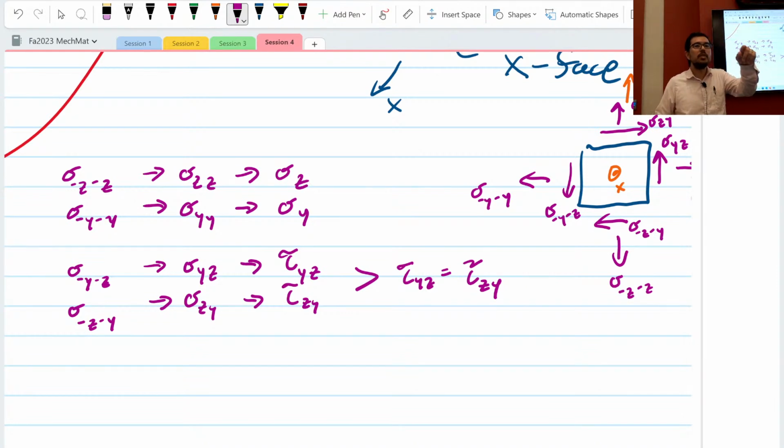Okay, and also, yes, you're right. One thing you said is that you get a lot of force with the scissors. From a mechanistic perspective, you do get a lot of force per small area. So with a scissors or a shear, you can crank up that shear stress really high. If I'm trying to pull this apart like this, I've got all this area. But if I go this way, I've got a little bitty area that I'm working on, and I can get all that force, so I can get high shear stress. So that's another reason why scissors. All right. Okay.